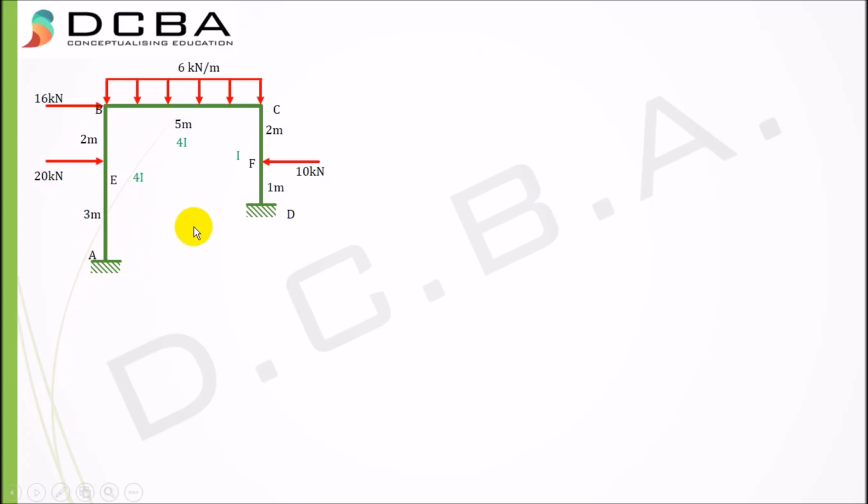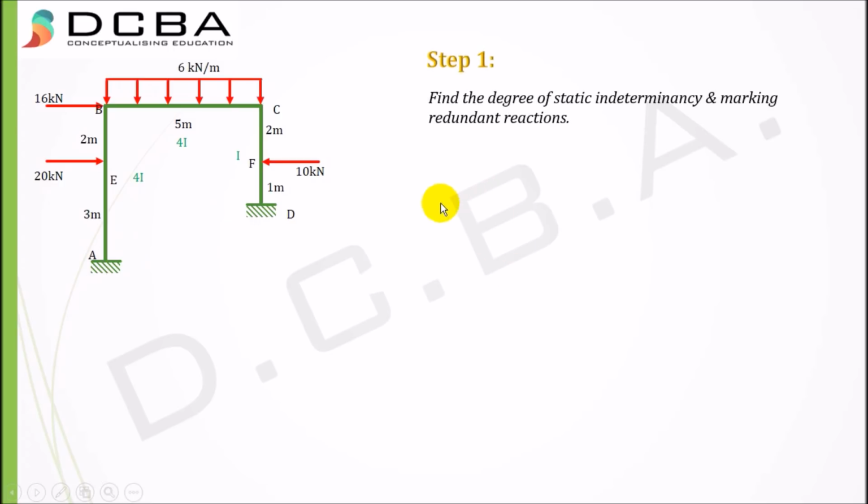If you have seen my previous video on the flexibility matrix, it comprises 5 steps. Step 1 is to find the degree of static indeterminacy and mark the redundants. The degree of static indeterminacy for a frame, or for that matter any structure, comprises two parts: internal static indeterminacy and external. For internal, as you can see, this is an open frame that does not have any loops, so the internal static indeterminacy is 0. The external would be all the reactions, 3 here and 3 here, so 6, minus the number of equilibrium conditions, that is 3. So R minus r, where the equilibrium conditions are summation Fx, summation Fy and summation M equal to 0. So 6 minus 3 is 3.